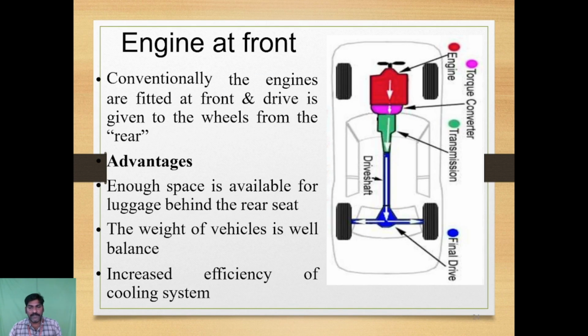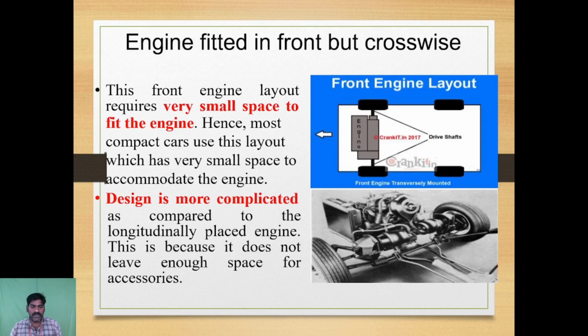Engine at front. Conventionally, the engine is fitted at the front and drive is given to the wheels from the rear. Advantages. First one, enough space is available for luggage behind the rear seat. Second one, the weight of the vehicle is well balanced. Third one, increased efficiency of the cooling system.